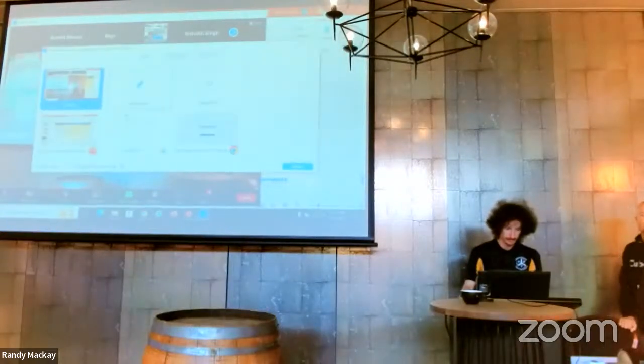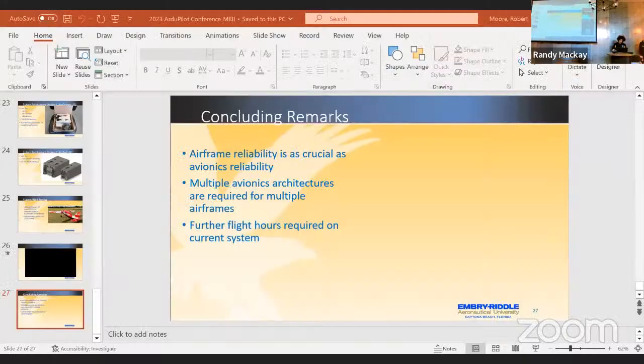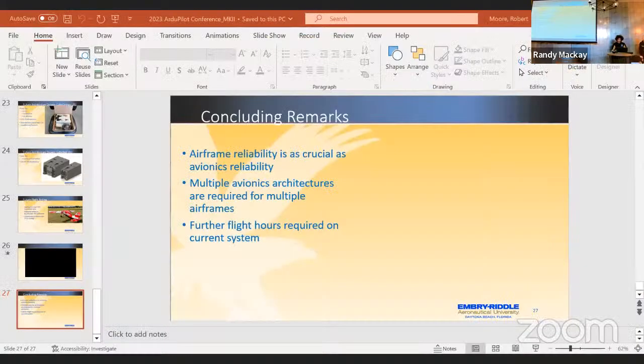The way I designed standby mode was that it basically follows everything, so it takes all the same inputs. If you change mode, it'll follow those modes, but internally it prevents the integrator build-up of position controls, attitude controls, and all that sort of stuff.